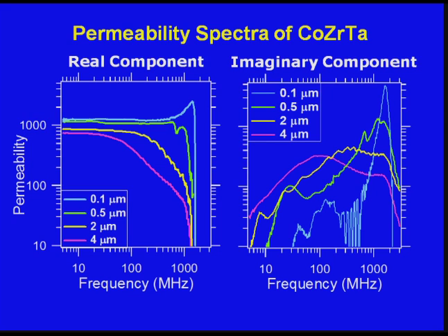Remember, we were trying to make our buck converters operate above 1 megahertz. We want to push them up to hundreds of megahertz. Well, if you look here at 100 megahertz, you can see that roll-off starts to happen as you increase your magnetic film thickness. So that means you're going to have trade-offs now. If you're going to saturate your magnetic material, then it's useless when you start dealing with tens of amps. So you have to pay attention to this.